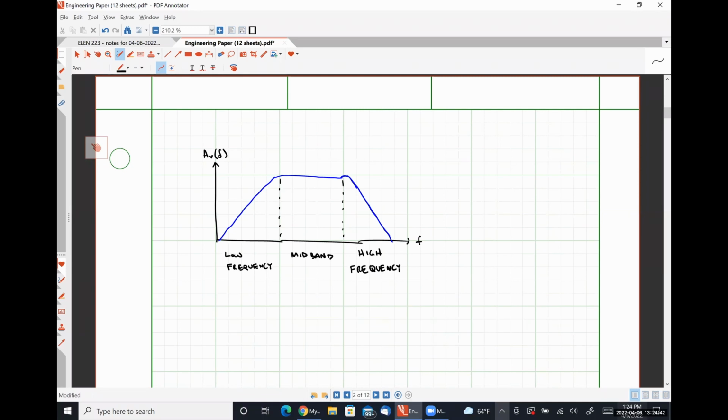So we'll see that depending on the amount of feedback applied, which gets into feedback amplifiers, another thing that we have yet to talk about, we can push poles one direction or the other in order to make our device stable over a large range of frequencies. That's how we get around instability problems, because anytime we have a pole, we have a potential for instability.